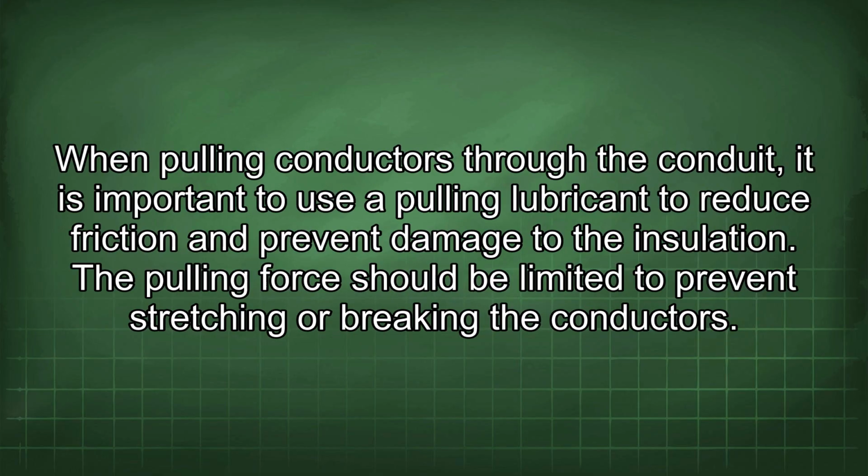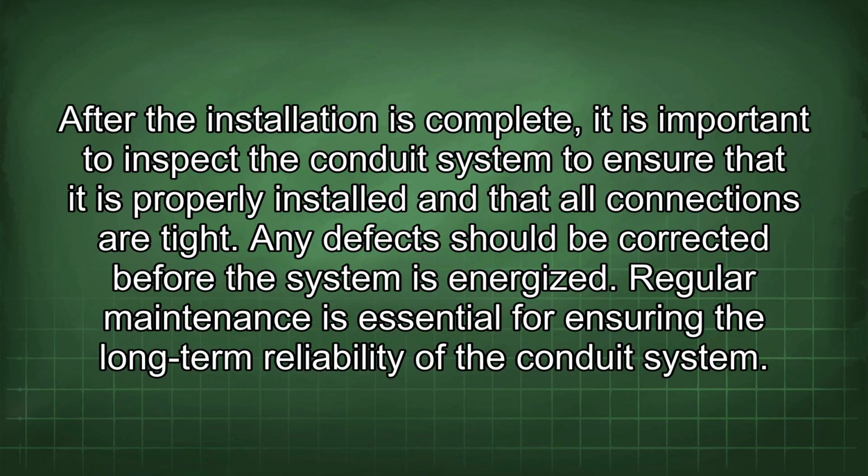When pulling conductors through the conduit, it is important to use a pulling lubricant to reduce friction and prevent damage to the insulation. The pulling force should be limited to prevent stretching or breaking the conductors. After the installation is complete, it is important to inspect the conduit system to ensure that it is properly installed and that all connections are tight. Any defects should be corrected before the system is energized.